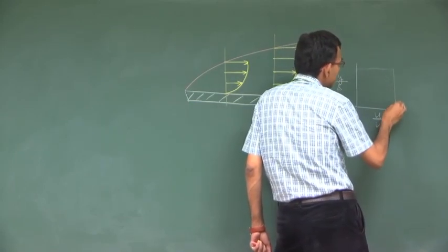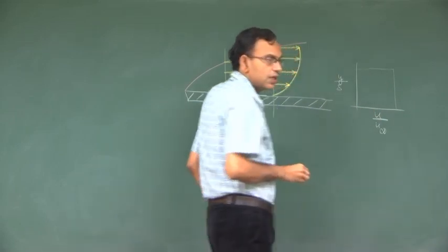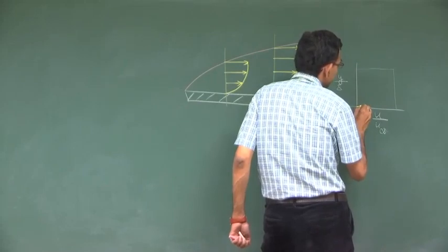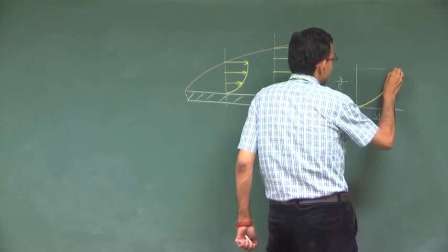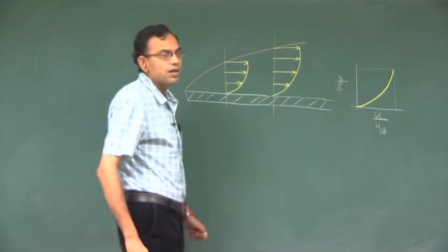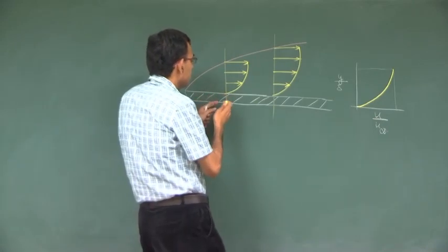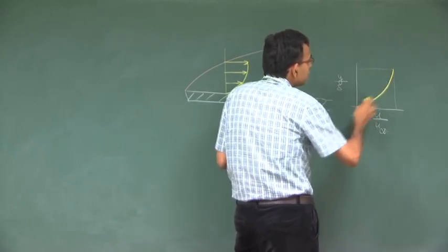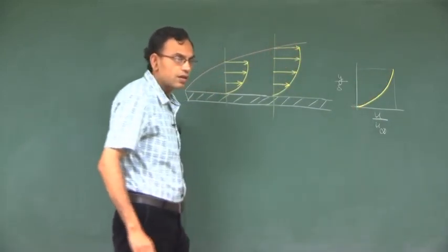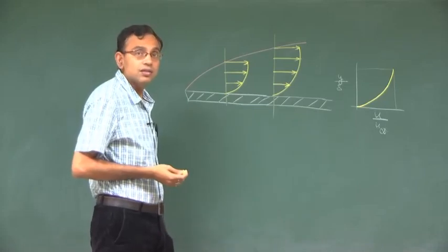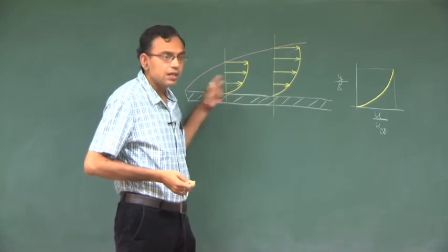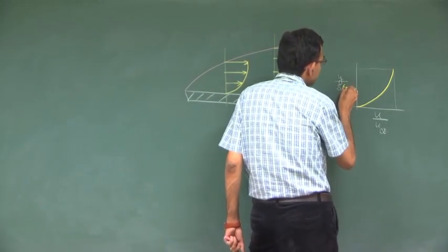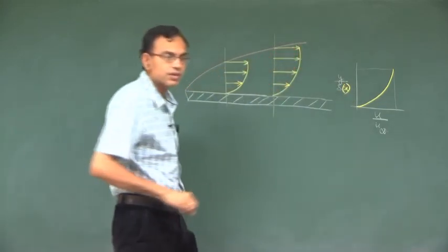So, the entire result is within a box of dimension 1 and you will see that interestingly all results, that is the velocity profile here, the velocity profile here, all converge to the single velocity profile. Where is the x dependence gone? The velocity profile is clearly dependent on x. So, where is that x dependence gone? The x dependence is here, this delta is a function of x.